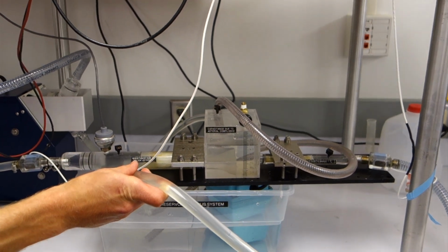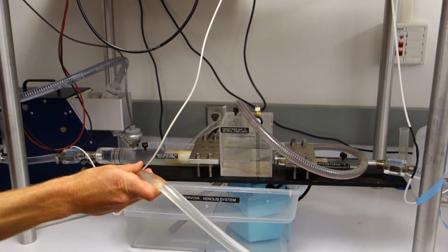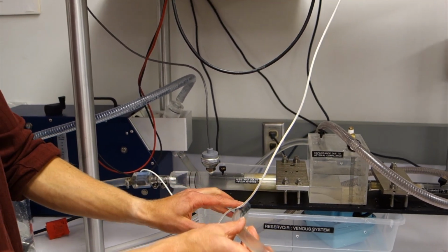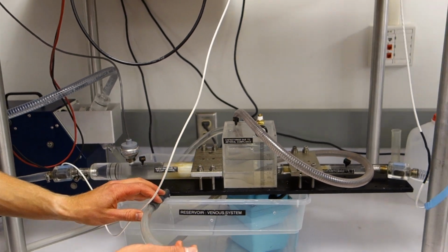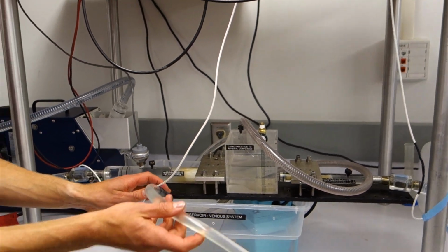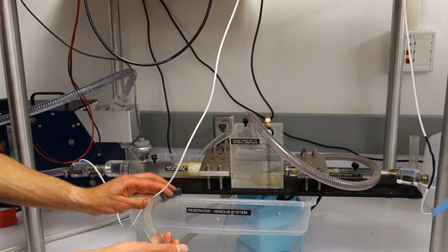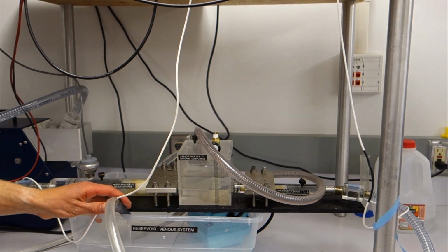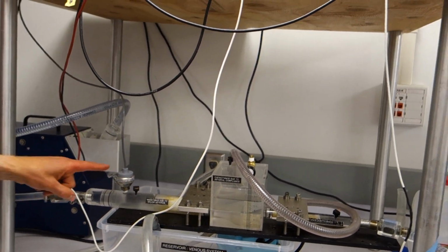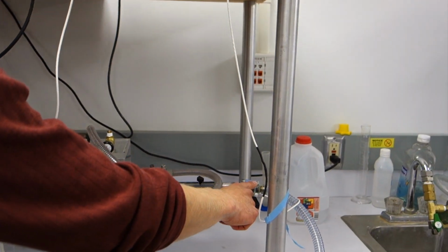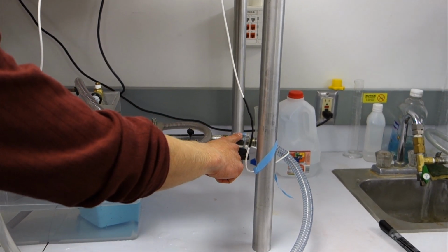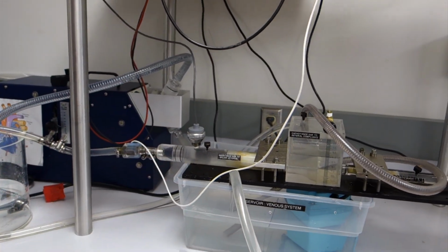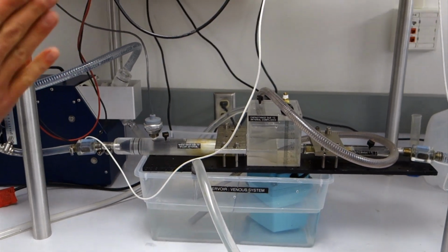Alright, and I want to take pressure and flow rate measurements at different voltages. So I'm going to turn it all the way down to 70 volts first. I'll have someone hold it here because we don't want to introduce any extra resistance. If I kink the tube or if I dip it under the water, then my output pressure will not be at atmospheric pressure, or I will introduce some different flow resistance here. In fact, I'll just hook it right like that. And I want to measure my P and my Q3 in voltages, and I'll convert them into millimeters of mercury and liters per minute. And then I will use the equation for flow resistance, or the relationship between pressure and Q, to get flow resistance.